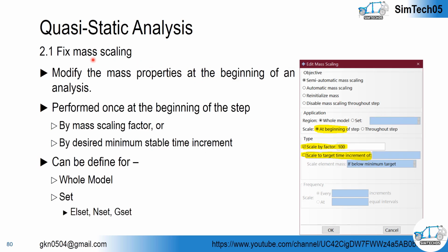So let's talk about the fixed mass scaling. As I told, fixed mass scaling we can define by scale factor as well as by time increment. Basically the fixed mass scaling technique is introduced at the beginning of the analysis, and the same mass matrix is carried throughout the simulation.